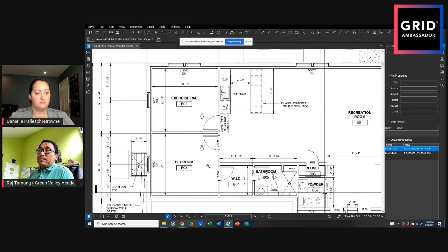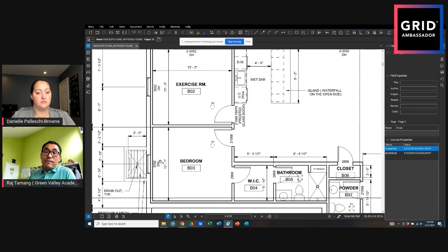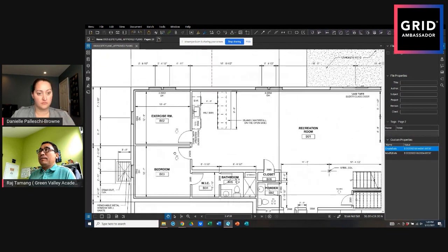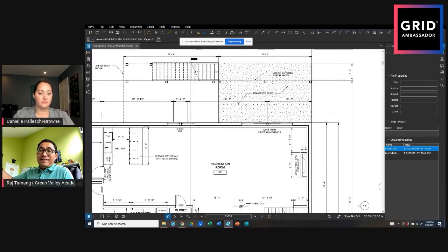It means when you call out a bedroom in the basement, you have to have egress doors and windows. Doors, of course, here, but the idea is in case of emergency, let's say there's a fire in the house, you should be able to escape from the window, right? So that's why you have to think about it. If it is a walkout basement, no problem. You just open the door and run away.